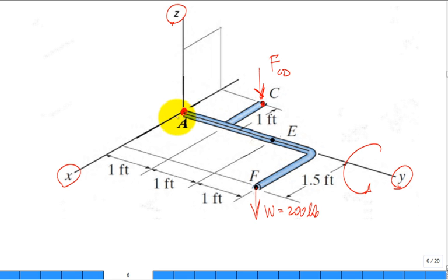And the ball and socket at A could generate on my object a non-zero reaction force in the X direction, and we would call that A in the X. Maybe A in the X will be zero. Maybe we'll have to conclude that it's zero. But in general, that ball and socket creates a reaction force on my object that could be a non-zero AX.